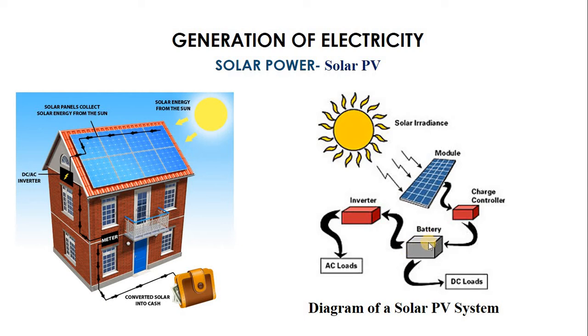Now if it doesn't go down fully, the battery doesn't become empty of power, and then the light energy from the sun becomes high again, and there's higher power from the solar module. This time the battery level just dropped a little, so the charge controller helps to top it up. That's what we call trickle charging. Top it up and it becomes fully charged. Now, when maybe you have used the battery overnight, because during the night there will be no power from the solar module.